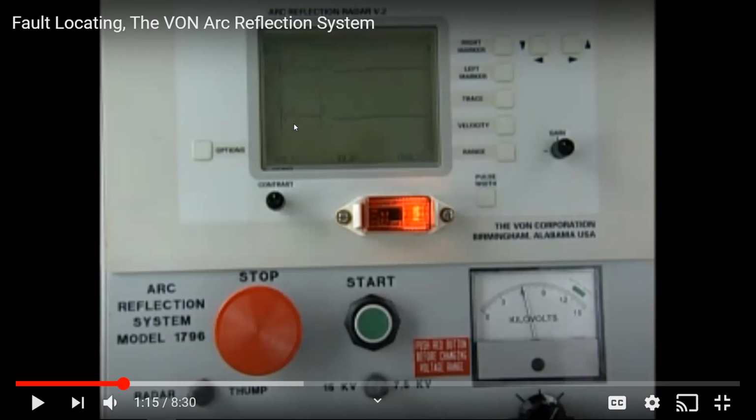All right, do consider this now. The wire's got to leave the transformer, go down, go the full distance. No ditch is exactly level all the way through. Underground primary cable might make turns. The longest span of underground primary cable I've pulled point to point is right around 3,200 feet. So this can get long. Radar mode gives you the general location in feet where you need to go. Once you've got it on radar, you can just take out a measuring wheel or whatever you need to do and walk down the suspected path of the underground primary cable.